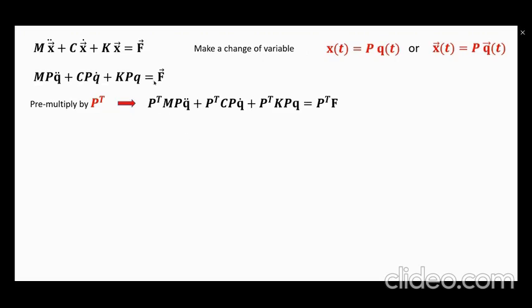This is your diagonal mass matrix, modal mass matrix. This is your diagonal stiffness matrix, modal stiffness matrix. This thing is going to be your diagonal damping. And we know when this is going to be damping. For example, either you enforce, you pretend that you just throw in two zeta I omega I, just plug it in, or you use, for example, Rayleigh damping to come up with the appropriate diagonal damping matrix.